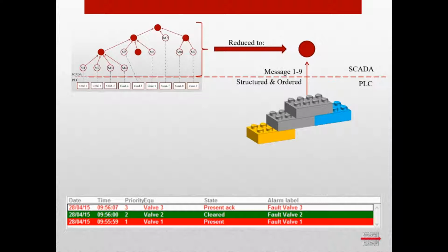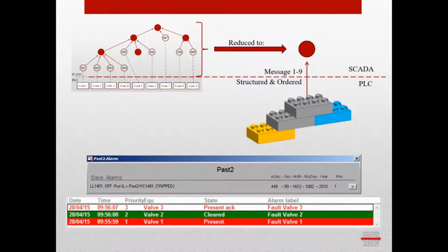In a conventional system, a message would look something like this. This raises a lot of questions to the operator. In PLC-Easy, a message always starts with the root cause, in this case, a level switch that turned off. The consequence, a protection interlock, the S88 pathway, and then the affected device and the state of the affected device. The operator is very much empowered by this information.